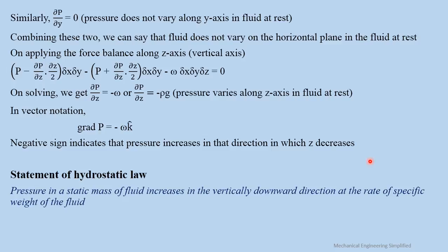It is a very important concept that above the datum surface the pressure decreases, and below the datum surface the pressure increases. This will be very useful in the calculation of pressure measurement devices, our manometers. So please make a very careful note of it. This is all about the mathematical expressions of the hydrostatic law.